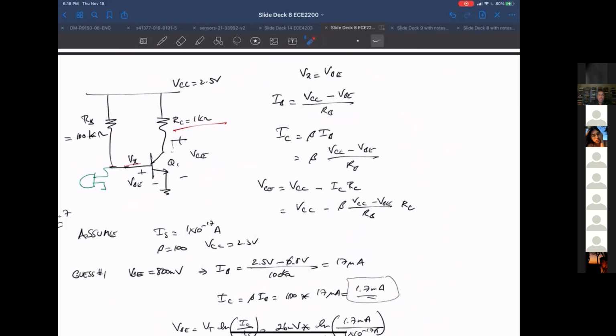And in no way is that going to be a single steady number from device to device. So if you make 10 of these circuits, of this really simple circuit, you're going to have to spend a bunch of time changing R sub B values for all 10 of them. And there's no way you're going to make this product economically. Imagine if in a real product, you might have tens, hundreds of different things like this.